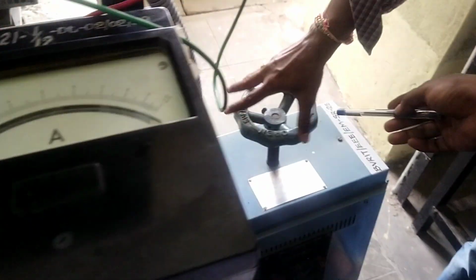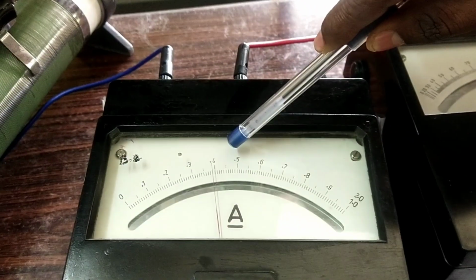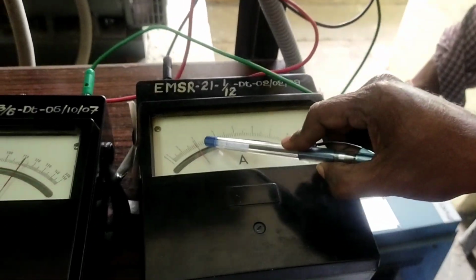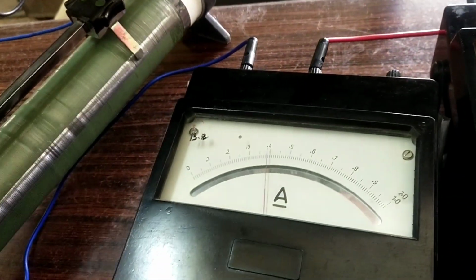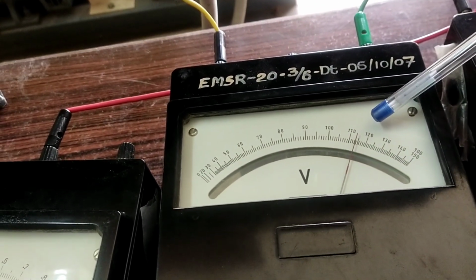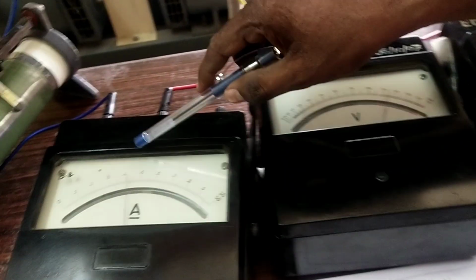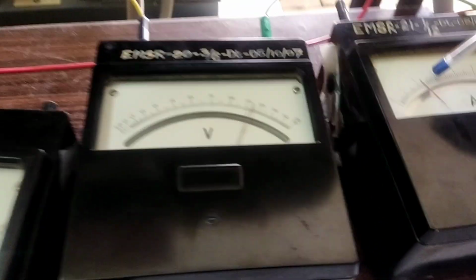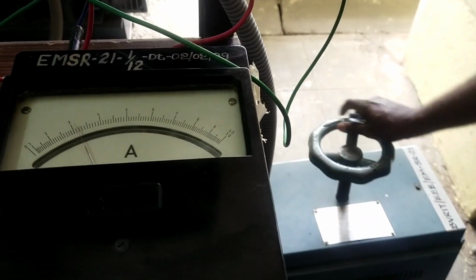The next step is to vary the inductive load. Currently we have 2 amperes short circuit current and 0.4 field current. Let us say this is my first reading. Next I adjust the inductive load so that the short circuit current is varied to 3 amperes, and the field current is 0.4. At this stage, if you observe, the voltage is reduced, so we have to increase it to make it constant. Now it is made constant, the field current is around 0.42, and the current is around 3.1. Because of the variation of voltage, a small variation is observed, and we need to take it into account. Again, the load is increased.